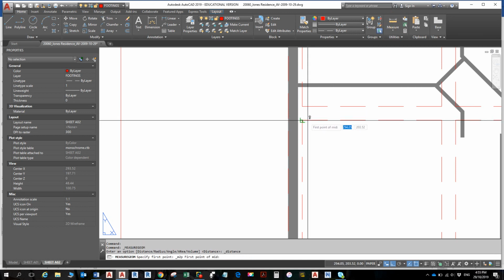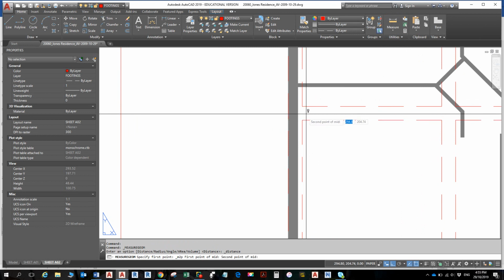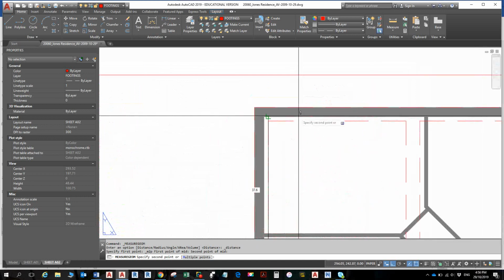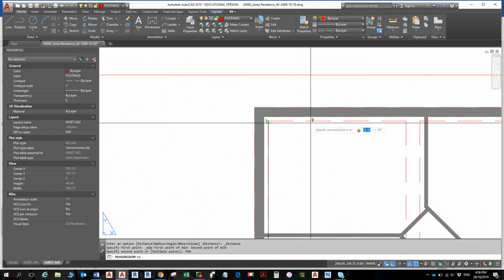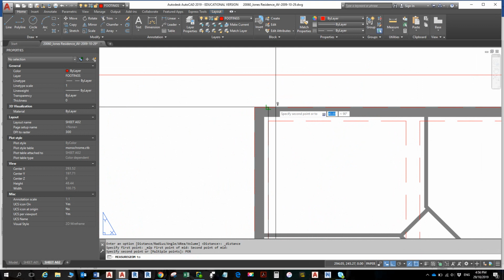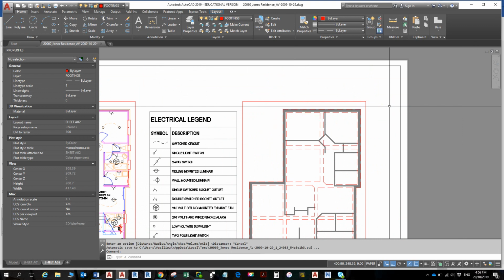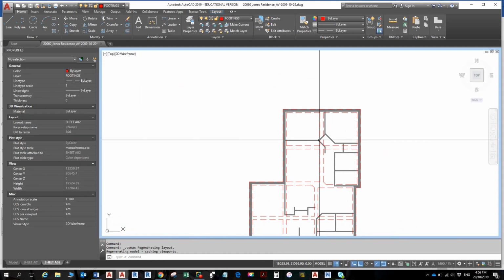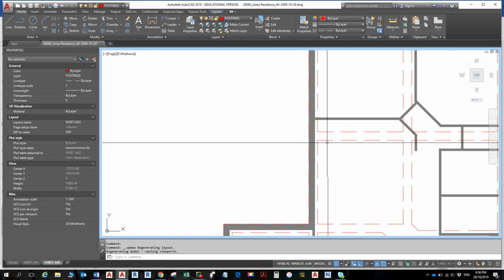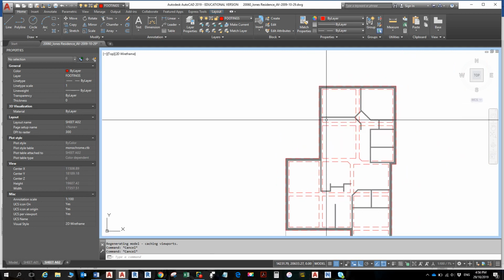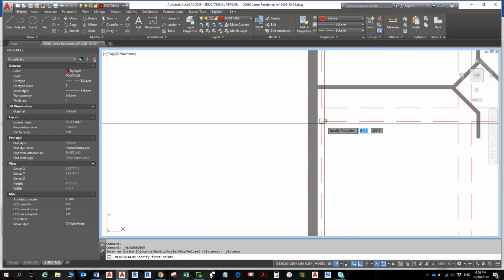And that bit hasn't. Look at this. Tab. Okay, from there we're going to go to perpendicular, PER shortcut. I'm single shift right clicking. It's 40 millimeters, it says, because it's just measuring for some reason on the sheet rather than down here. So if you were to add the extra 14 millimeters, that would change. How would it change it? Well, let's have a look. We're about to find out.